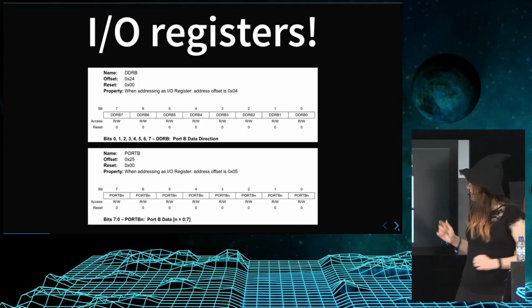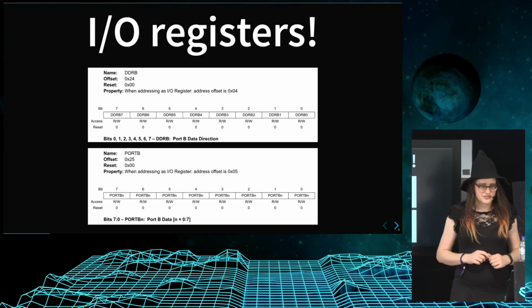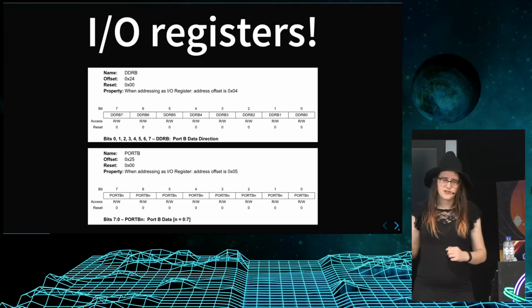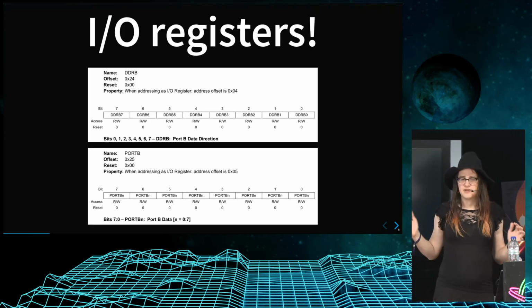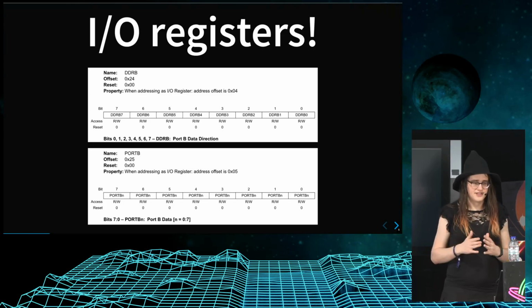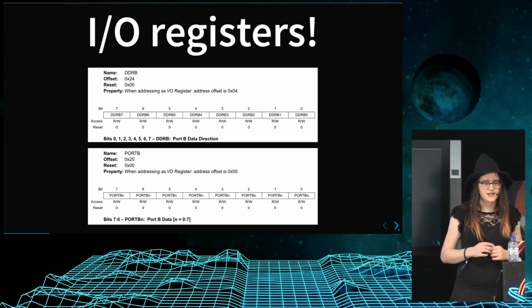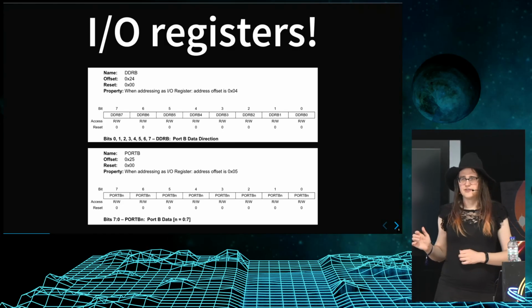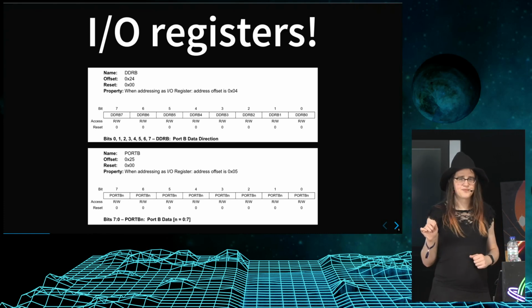And you can actually see them on screen here. So the offset here is the pointer address. And on the AVR, like on most microcontrollers, pins are grouped in ports. So 8 pins are grouped in one port and can be controlled together. So, for example, the Arduino Uno has an LED on pin 13.